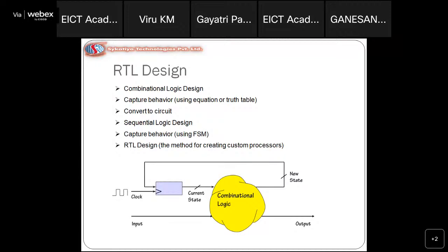In Altera FPGAs, if you're using Altera FPGAs, you have to use the Quartus tool. Based on your FPGAs, you have to use the specific tools. Then only can you download to the FPGAs. If you are using Xilinx FPGAs, you cannot use Quartus. For coding and synthesizing, you can use any tool, but when you are using the FPGAs, you have to download your design to the FPGAs.